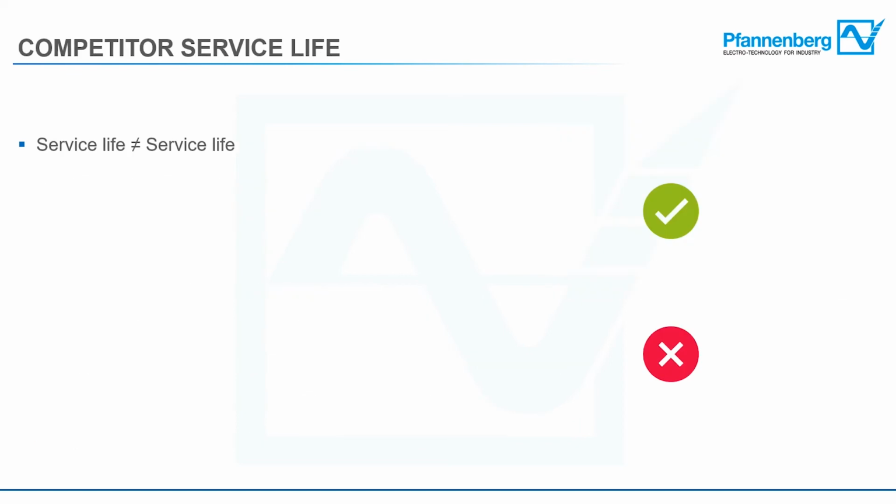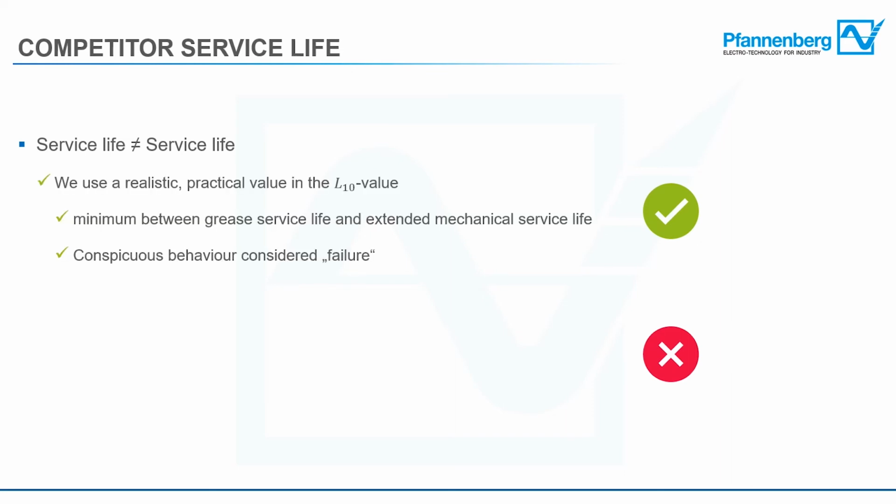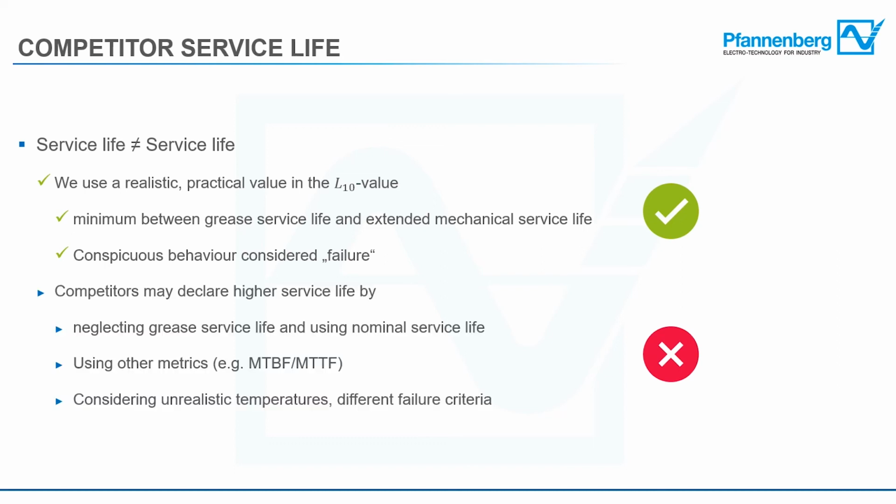So, in conclusion, it can be said that service life does not necessarily equal service life. In our case, we use a realistic practical value in the L10 value provided by our fan provider EBM Papst, which is the minimum between the grease service life and the extended mechanical service life. We also consider failure to be conspicuous behavior, which is obviously a more strict criterion than saying the fan doesn't work entirely, so it doesn't rotate at all.